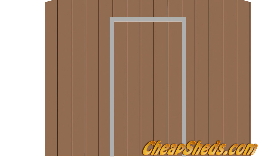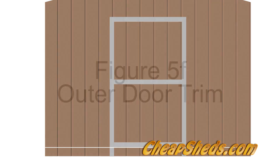Measure and cut 2 vertical pieces to run from the bottom of this piece to the bottom edge of the siding. Nail these 3/4 inch from their inside edge from top to bottom to within 2 inches of the bottom plate chalk line. Measure and cut the last 2 horizontal trim pieces. Position the middle piece of the trim so it's centered on the chalk line and nail it down the middle. Position the bottom piece of trim so the lower edge lies on the bottom plate chalk line and nail it 3/4 inch from its top edge.